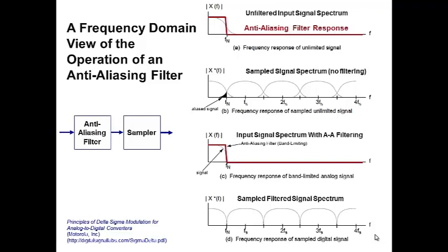Now, a couple of assumptions. We assumed that this stuff up here was something we don't care about. If we really did care about that, we should be sampling at a higher rate so that the Nyquist rate is higher. But if that's truly noise or stuff we don't care about, we're going to throw it away to keep it from aliasing and messing up our signal, the good parts.